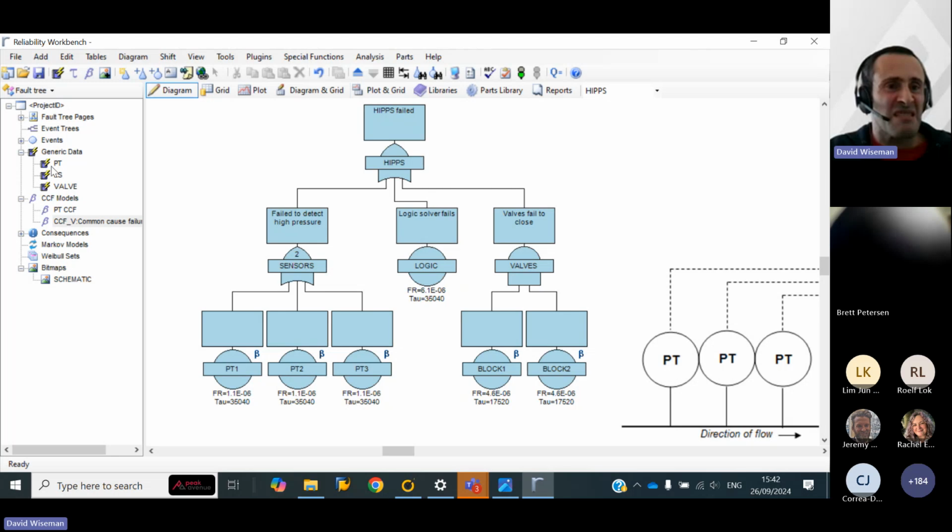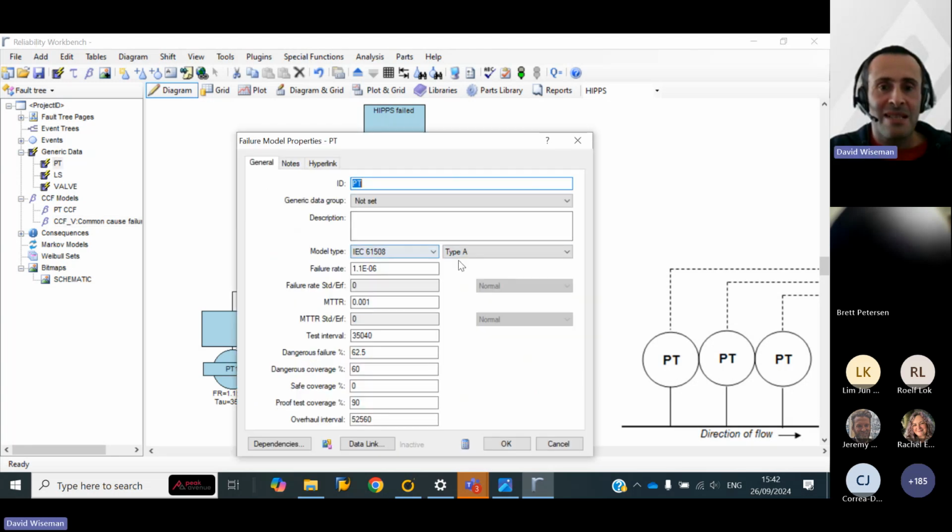You might have noticed there is a type option in the 61508 model, type A and type B. This refers to a table, if I remember, it's in part 2 of IEC 61508, where you can estimate hardware fault tolerances based on the safe failure fraction for the piece of hardware and basically the quality or how well you know that system, how well understood it is. A is the best, B, you don't know it quite so well.